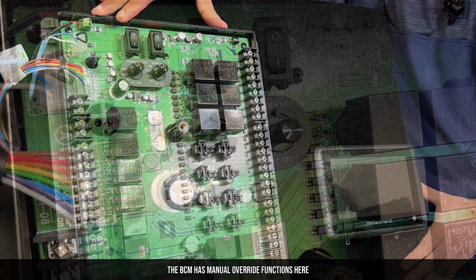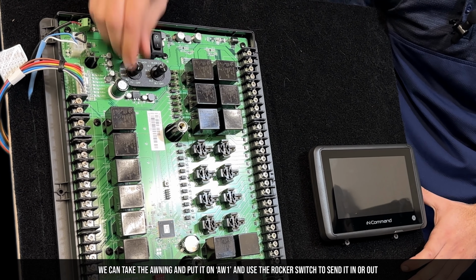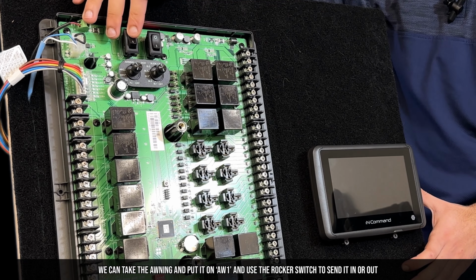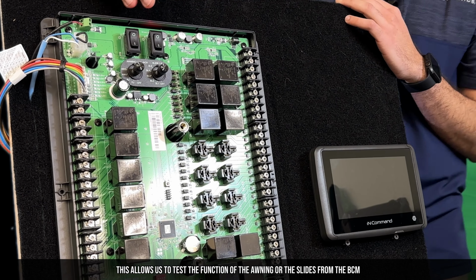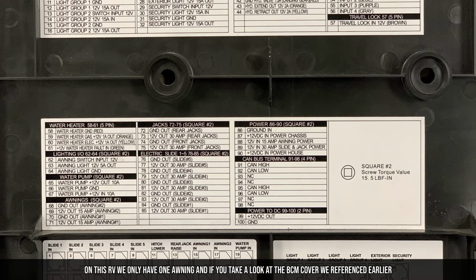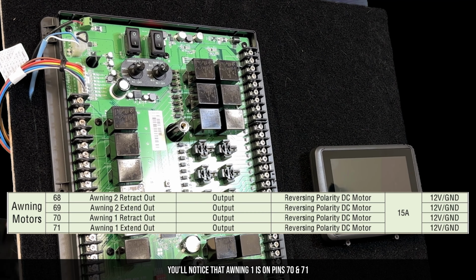The BCM has manual override functions here. This is the awning knob and this is the slide knob. So we can take the awning and put it on number 1 and use the rocker switch to send it in or out. This allows us to test the function of the awning or the slides from the BCM. On this RV, we only have one awning. And if you take a look at the BCM cover that we referenced earlier, you'll notice that awning number 1 is on pin 70 and 71.